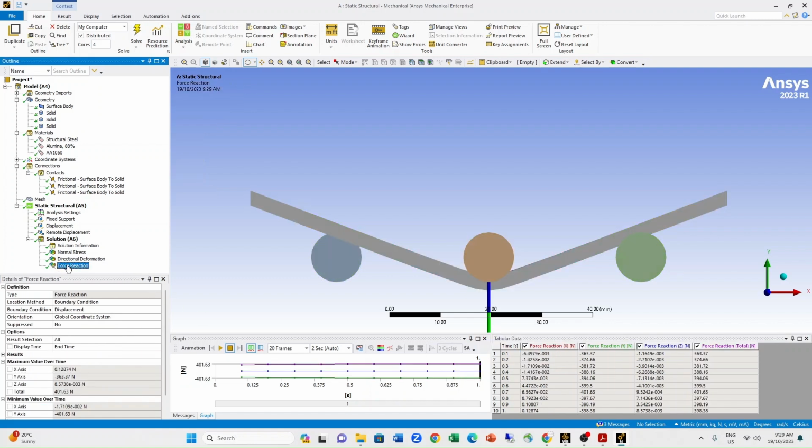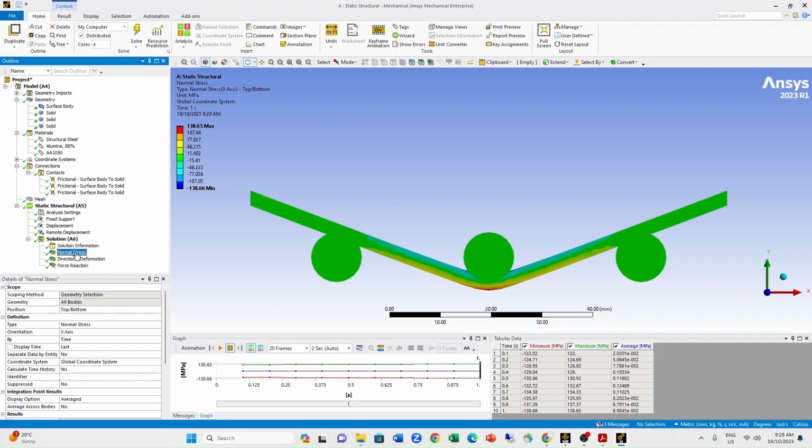The reaction force uses the same time reference, so it can also be copied to an Excel spreadsheet. So we can get the force displacement curve from the simulation.